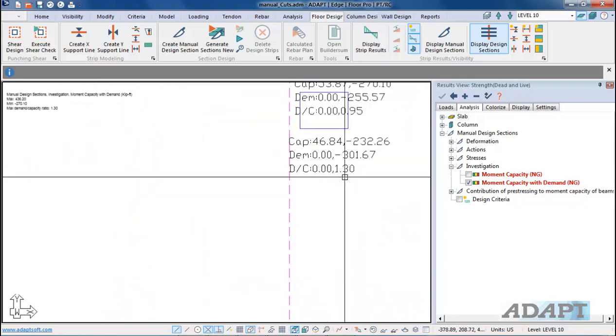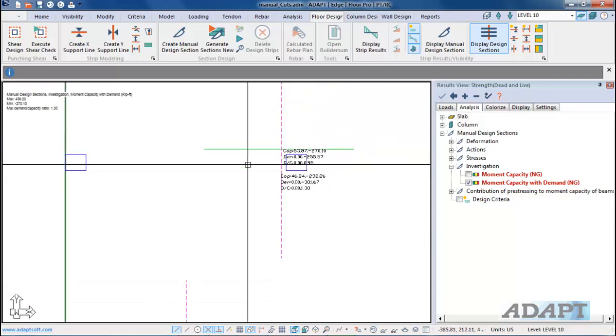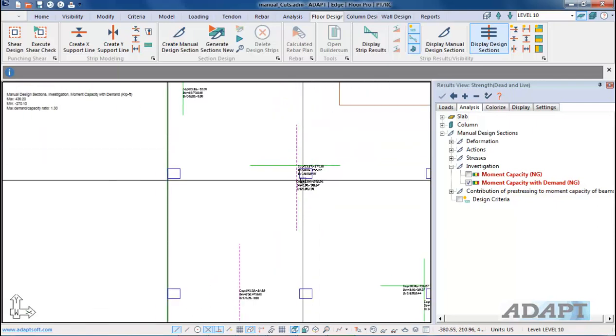And this capacity that we're looking at is derived again from the concrete and the base reinforcement that's been entered into the model. In this case, the only base rebar is the post-tensioning. So we could add some localized bars in these locations to go back and check capacity if those bars are reflective of what you're checking for an existing condition.